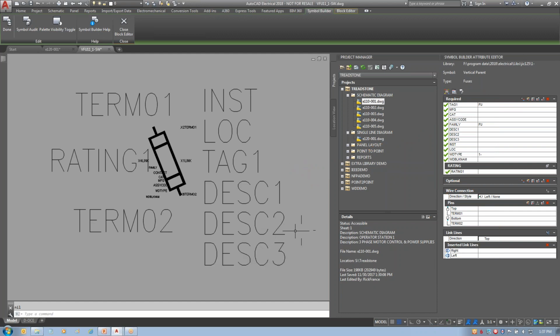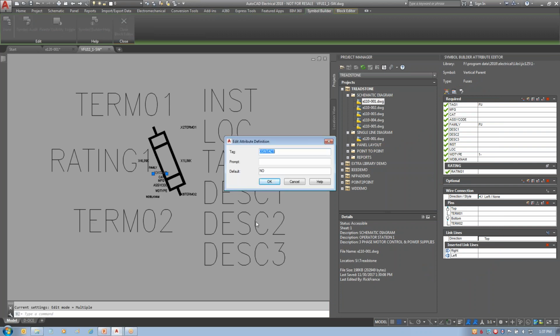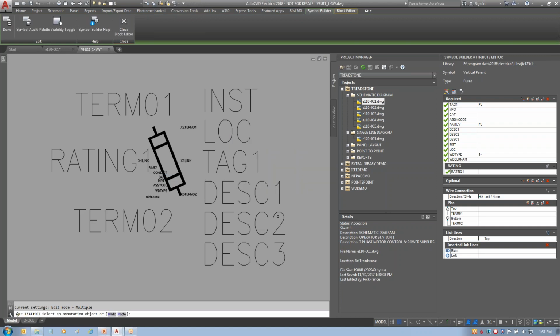The only difference is, one thing I had to do custom is I added this contact attribute that was not there originally, and it's basically the one that defines whether it's normally open or normally closed. So I've got the contact one in there for the normally open. It's the same attribute that would be in a normally open, normally closed symbol that you created that was a regular component. But the main difference here is this one called WD type, which is right here.